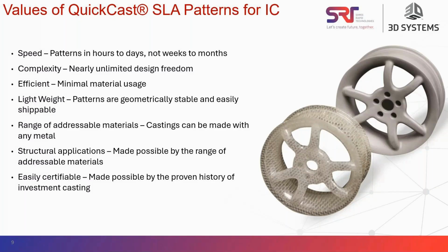The pattern that previously took weeks or months can now be made in hours or days. So it is not only faster, it allows engineers or designers to make designs which were previously not manufacturable. They use less material, more efficient. In the traditional method, you might be aware, you need 100% solid wax. Now it's almost 90% air.